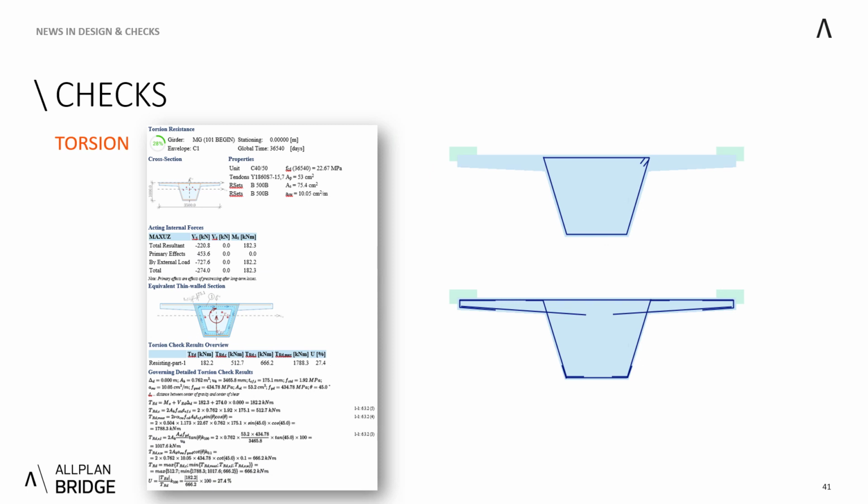Coming to the torsion, as I have explained at the beginning, there are two approaches to the reinforcement. In this example we used the real geometry, which can be represented in a real-life project as two types. You can have in mind the top approach, that is one closed stirrup that is effective in torsion, or it can also represent the calculation stirrup for this type of longitudinal reinforcement that is forming torsionally effective reinforcement.